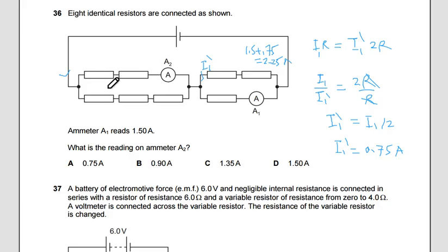Okay, this current is the same that enters here at this point and also divides. And again, the potential difference is the same for the two branches. So the current I2 that enters here is inversely, let me just name this as I2 dash. So I2 dash over I2 will be 2R over 3R.